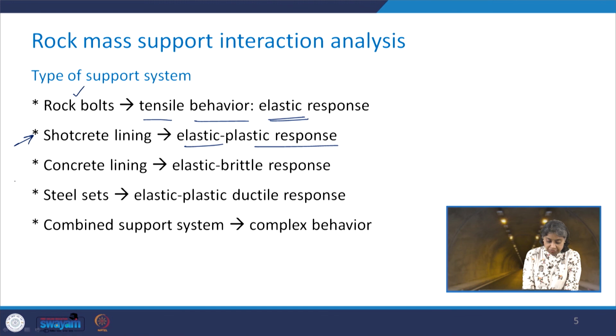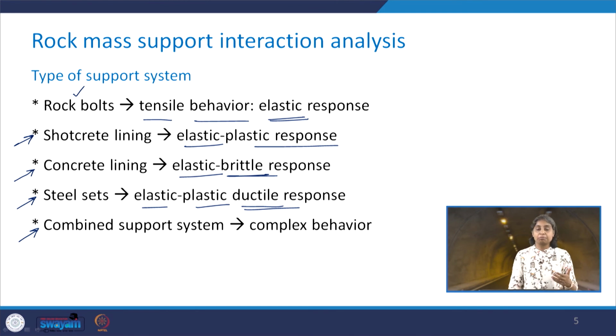Similar is for the concrete lining, but here it is elastic and brittle response. For the steel sets, it is elastic plastic, but it is ductile response. And in case you have the combined support system, then it is going to show you complex behavior.